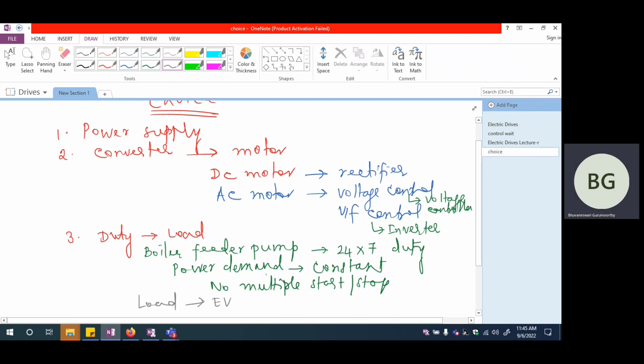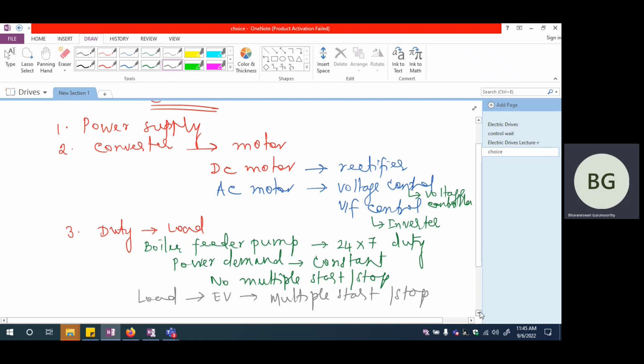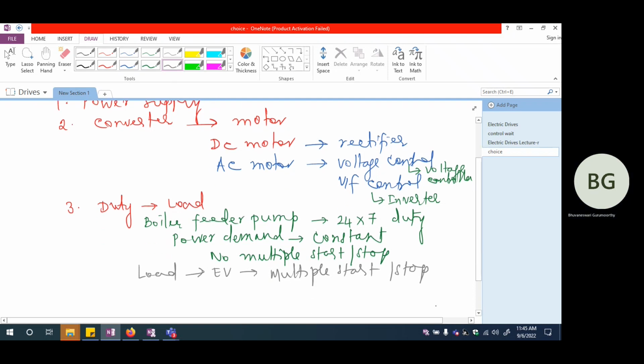obviously, you're not going to run the vehicle continuously. If you see a red light on the road, you have to stop. If you want to avert an accident, you have to stop. So you will definitely have multiple start and stop. So when you are starting, the current drawn may be very high for your machine. And similarly, when you are stopping, again, you may employ regenerative braking. Again, the current through the machine may be somewhat larger. So these will really require very good transient operation also for the machine.